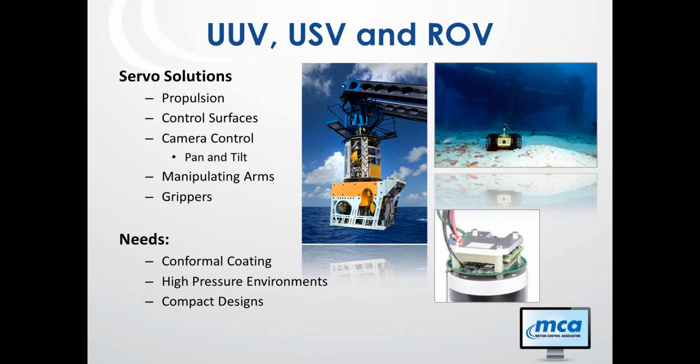A little bit more what you really need to focus on with these bots is the conformal coating. You're dealing with condensation or high humidity environments, salt water. You're also dealing with very high pressure environments. When you go deep under the ocean surface, you deal with very high pressures. How do your components handle that? How do you deal with air when it gets compressed? You need to think about that when you're designing that system.